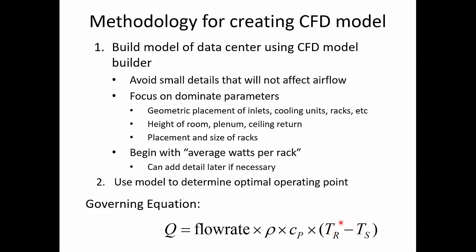Of all these devices, it's the same equation for servers as it is for cooling units. What you're hoping to do is get the delta Ts to be the same on the cooling units as they are in the average of the racks. You want to balance the heat transfer in the room.